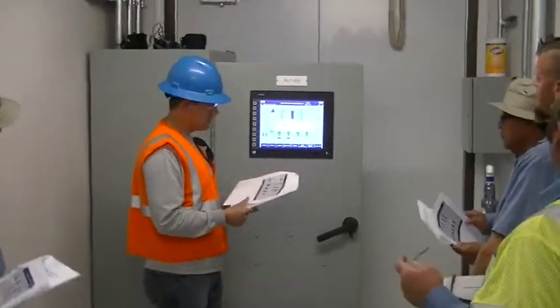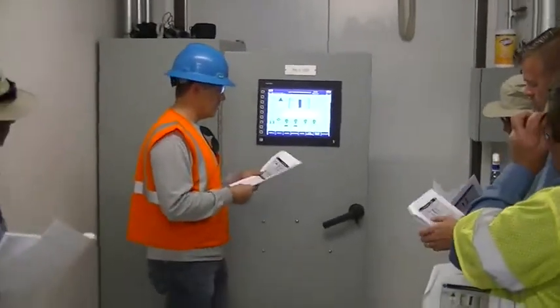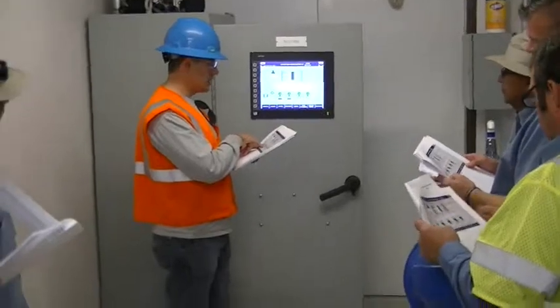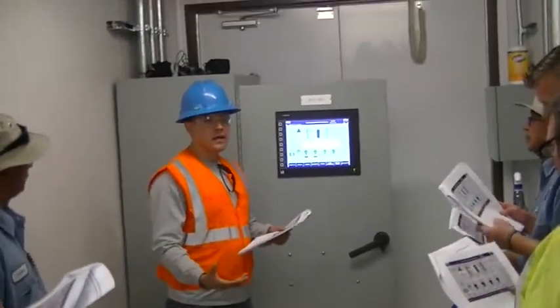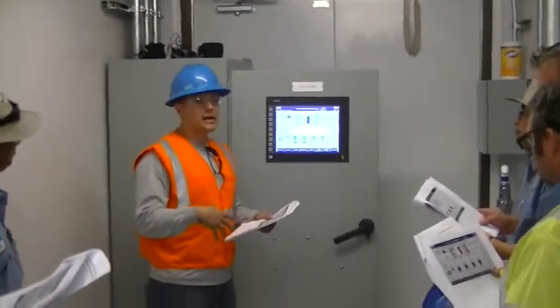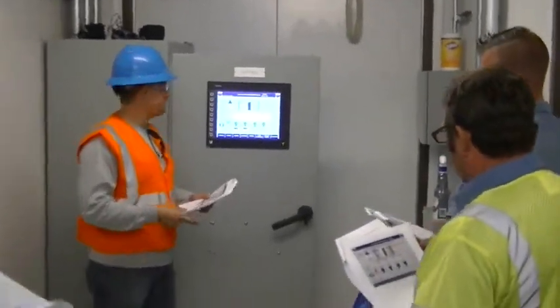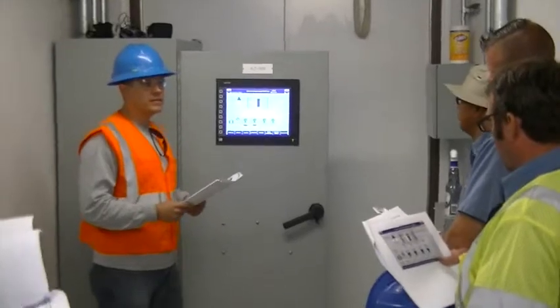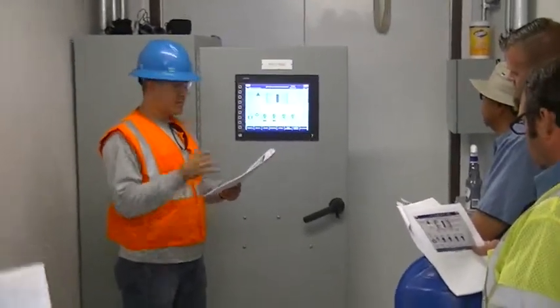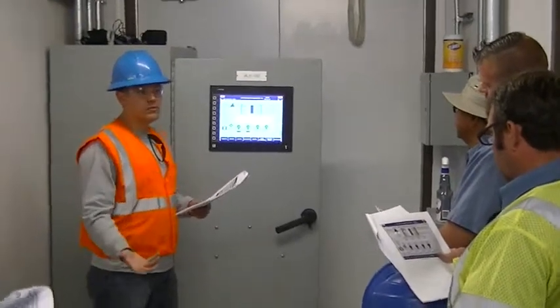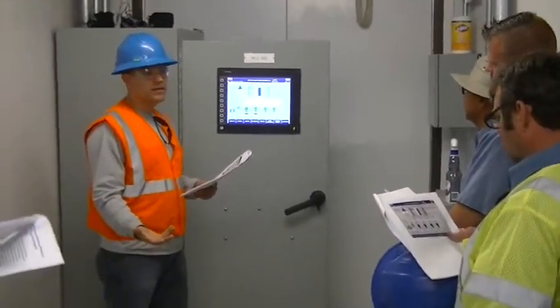So the alarms that happen with the motors are fail to respond, which is basically you're called to run, and you don't get a running signal back in a certain amount of time. And that's settable in there. I'll take you to the set points on there. But that'll be your fail. It will flip over, if that's the lead, it'll flip over to the lag pump to turn it on if it gets that fail to run